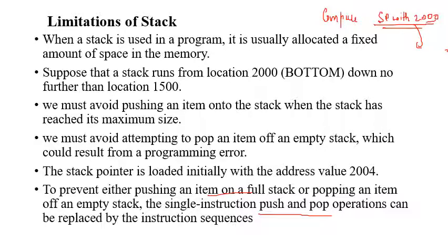Similarly, you can avoid popping the data from the empty stack. You need to compare the stack pointer value with 1500 instead of 2000.